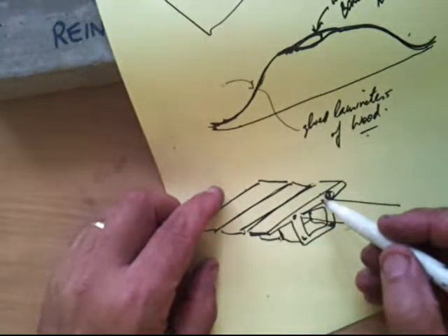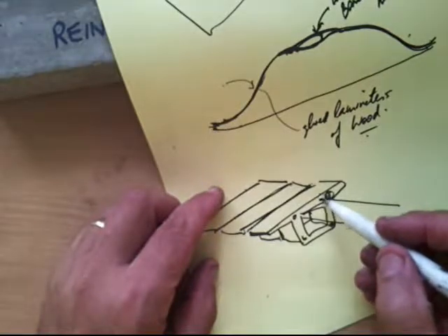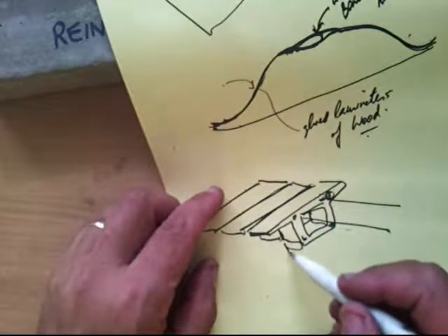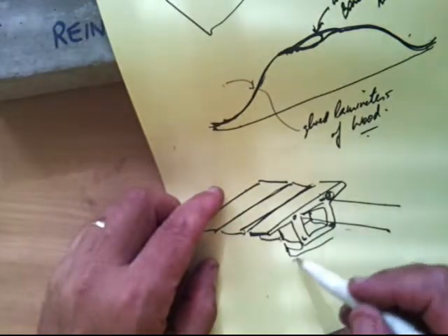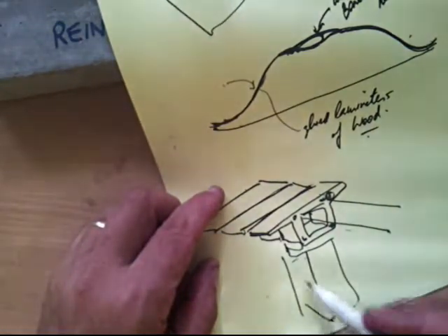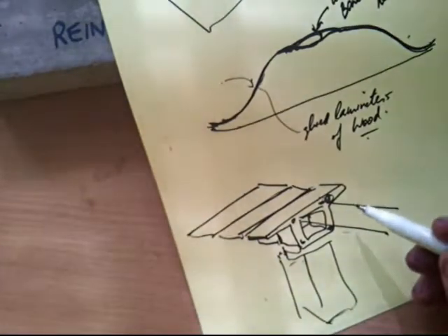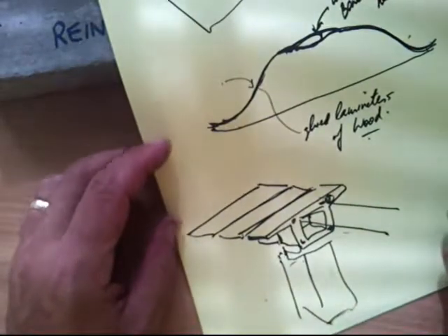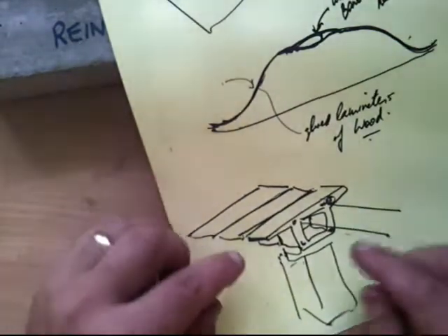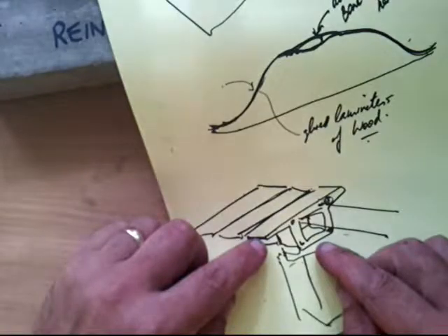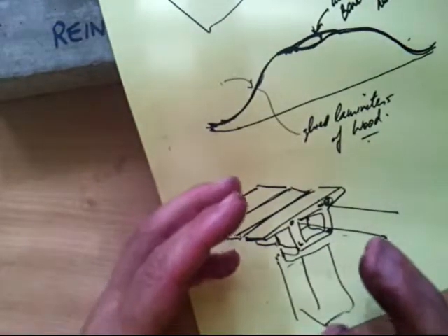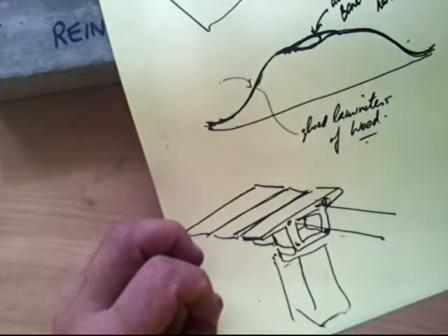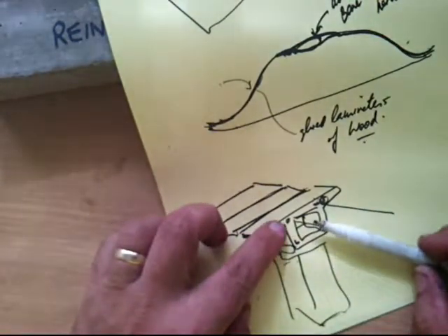And what will happen here is these sections will also be glued together as well as post-stressed, and there'll be some locating pins and things like that to hold them all together. And that's often how a suspended roadway will be sitting on a column, and the suspended roadway will be set up like that. And you'll see these sorts of things, and you'll see the joints on them as you go. So that's post-stressing, and very useful when you need to reduce the weight of a member, and you can control very much the kind of compressive stresses that are placed under the assembly.